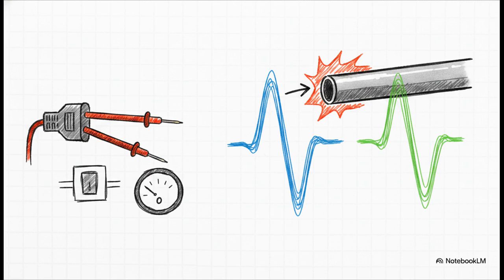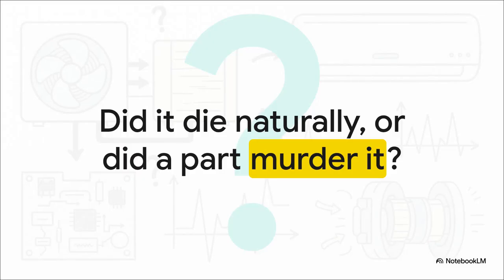And remember, the board doesn't just use these sensors for hard emergency shutdowns. It's actively monitoring that pressure and the thermistor data to proactively limit the compressor's hertz frequency. For example, if the discharge line starts getting way too hot, the board will automatically slow the compressor down to prevent catastrophic damage way before a trip even occurs. It's protecting itself.